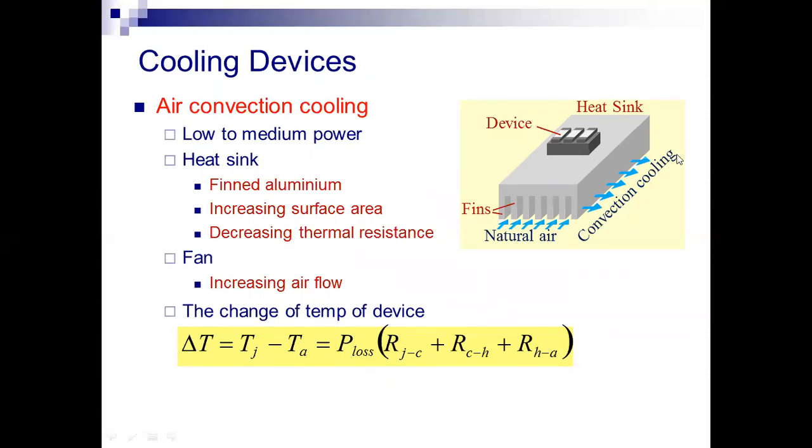In all the inverters which we are placing here, these are the cooling devices for the IGBT switches or the MOSFETs. The fins are placed here, natural air moves towards the fins, and after the air is convected it comes outward. The cooling is considered a convection process, that is convection cooling, and this is completely a heat sink.